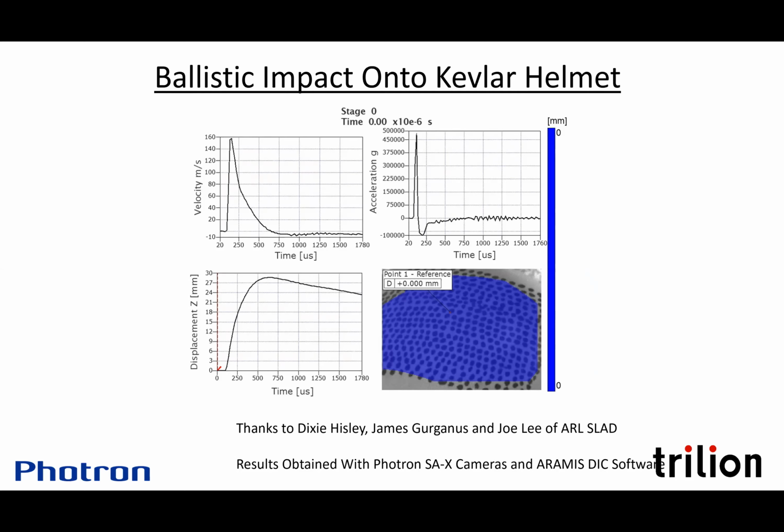Normally with DIC, we're working in the time domain, and in the time domain, we simply need enough microns of displacement. That's going down as frequency goes up. So I can't give you a firm number for a cutoff frequency, but it's, are we able to excite enough displacement? And that does get tougher at higher frequencies.